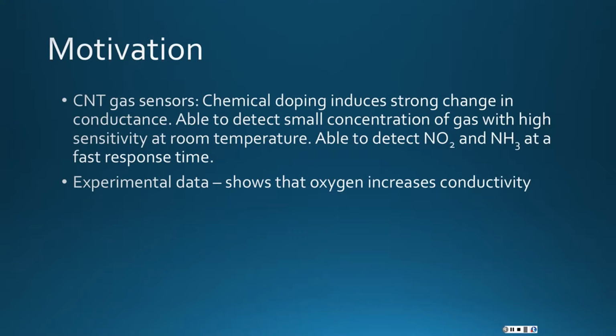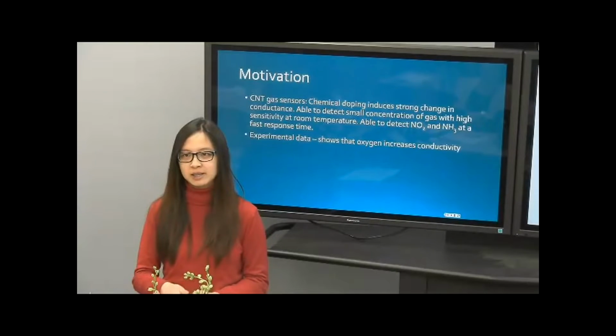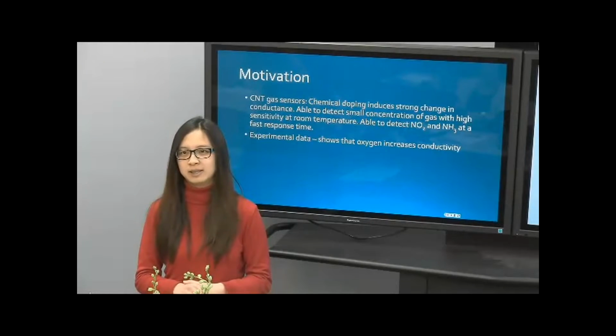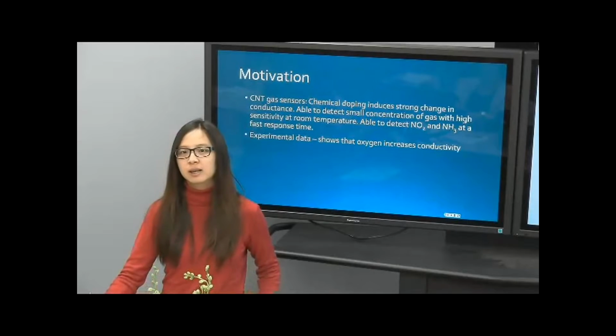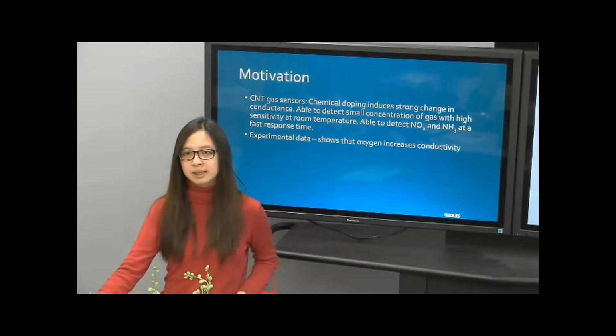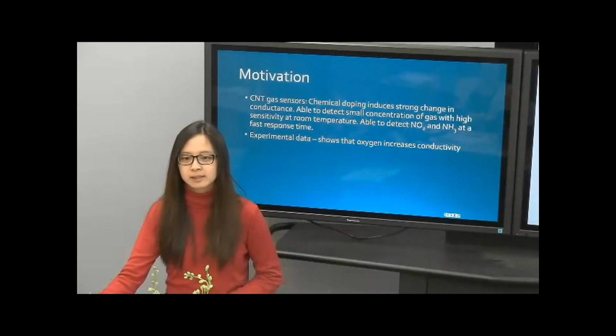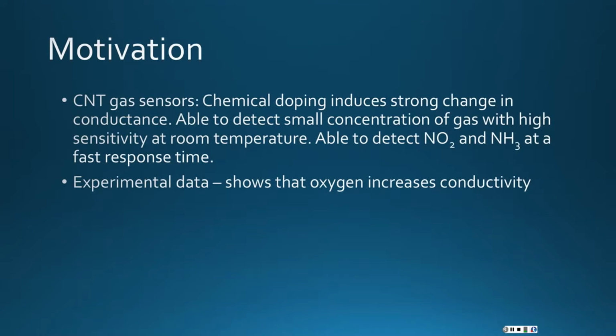For gas sensors, it can induce a strong change in conductance, and then the carbon nanotube can be used to detect gases such as NO2 and NH3 or oxygen, and experimental data has shown that oxygen increases conductivity. So we are using computational methods to look at this.